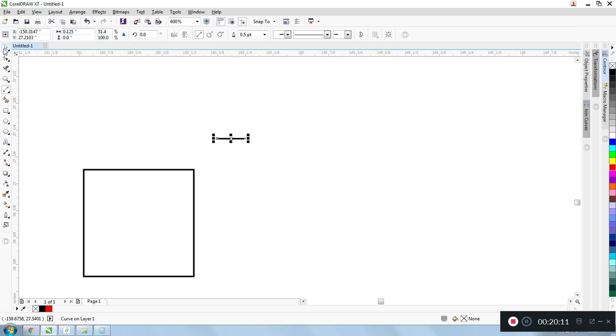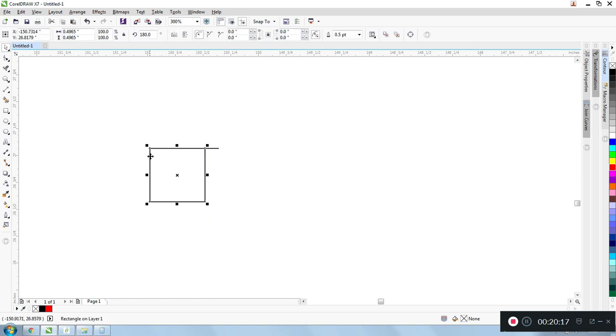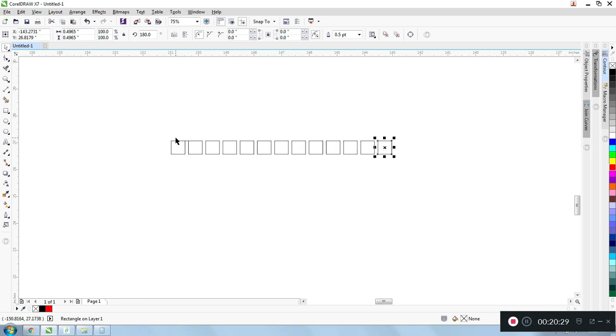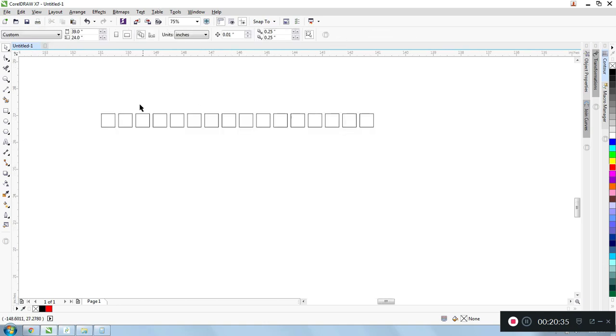So now I have a 1/8 inch line, and I select this object again, I move it, snap it to this node. Oops, I forgot to hit Control D. Okay, Control D, snap it to this one, and then as I go, hit Control D again, it just makes as many of those as I want. And then I delete my measurement line, and yeah, pretty handy.